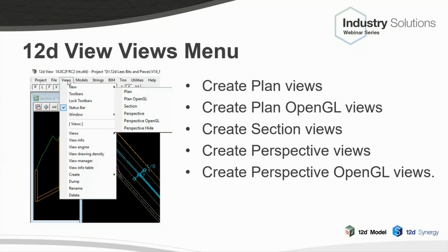The section views, as the thing about section views, yes, you can just do a cross section where it's just across a straight line, but you can have bend cross sections. You can also profile down alignment strings where it's got curves and things in it. So it's not just a cutting in a 3D view, it actually is much more important than that, and also projects things down onto the section. So that's why we have those views and why just saying one view type can't do it all, because there's different things that go with each view. And 12D view has all those properties so they can use them.